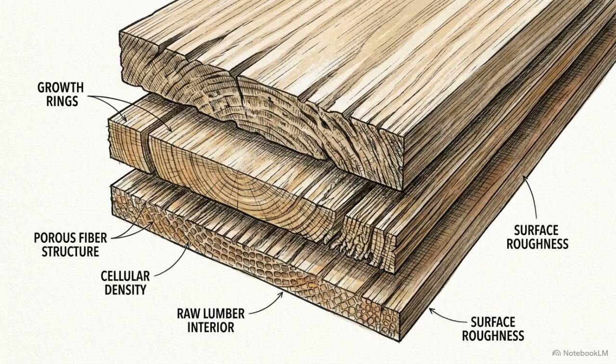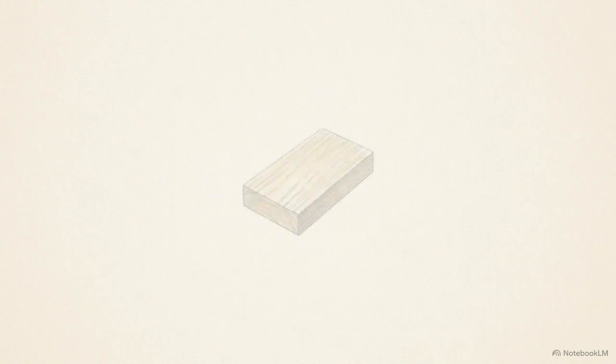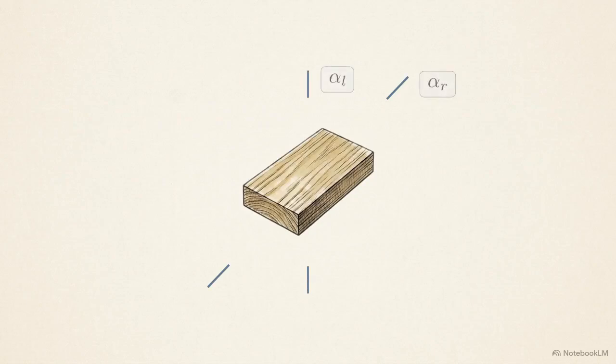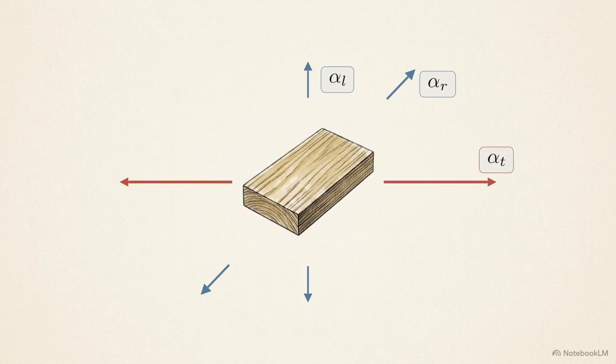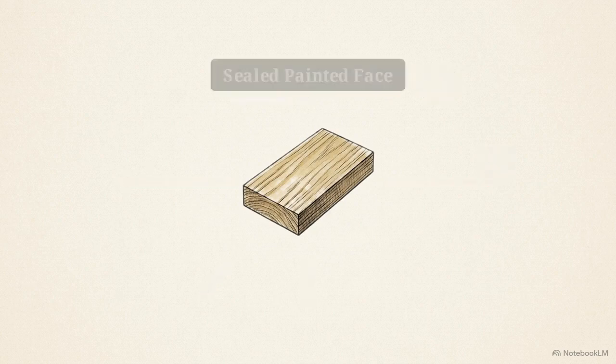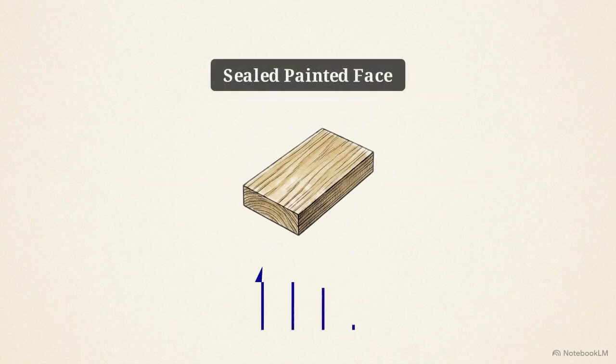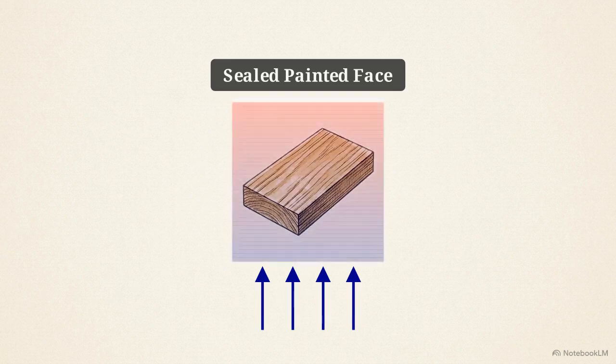The foundation of the system is a single flat sawn panel of white poplar, Populus alba L. This wood exhibits anisotropic properties, meaning it expands and contracts at different rates in different directions. Its tangential expansion rate is significantly greater than its radial or longitudinal expansion. Because the painted front face is sealed, moisture can only enter or leave through the unpainted back.